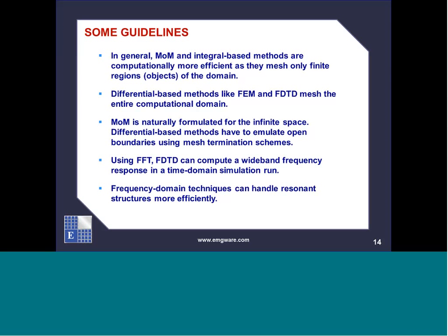There is another issue. Method of moments is naturally formulated for infinite space, and we are going to come back to this, because of using the Green's functions. So we can basically model the entire infinite space using some analytical expressions. But in differential-based methods, you have to emulate the open boundaries using some sort of mesh termination scheme. For example, if you have a patch antenna on a dielectric substrate, you cannot just take the infinite substrate, so you have to cut it, terminate it somehow into a finite region, and discretize the finite computational domain. Therefore, you have to use some sort of mesh termination technique, like radiation boundary conditions, or absorbing boundary conditions, or PML, perfectly matched layers.